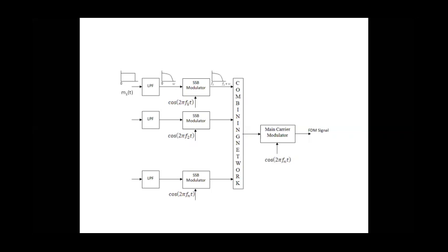Okay, the SSB modulated signal with upper sideband is simply called a frequency translated version. To which frequency? F1. Okay. So before SSB modulation, the signal is having a frequency from 0 to W. After SSB modulation, it is ranging from F1 to F1 plus W. So this is about the first message signal.